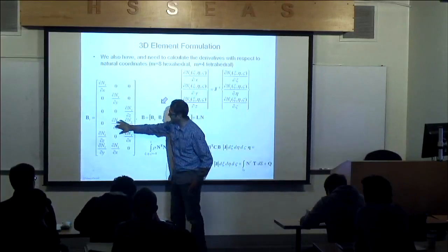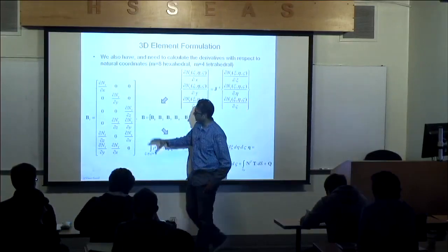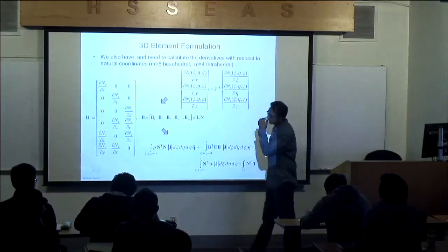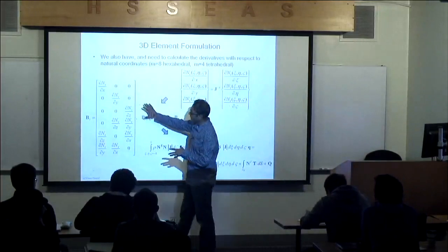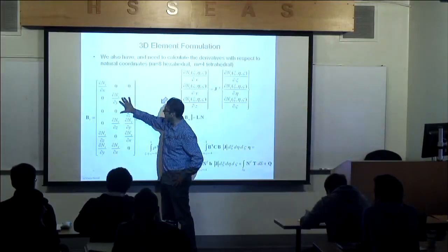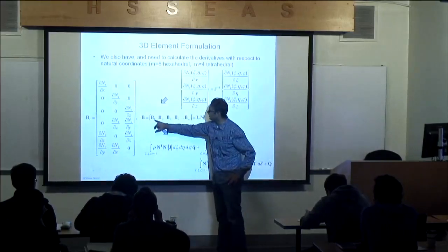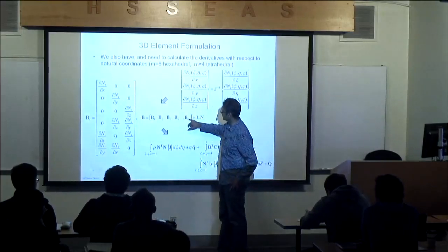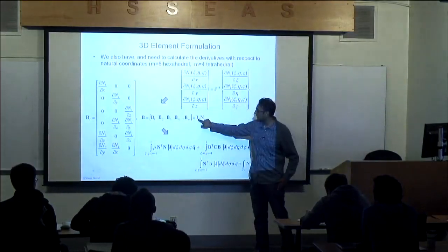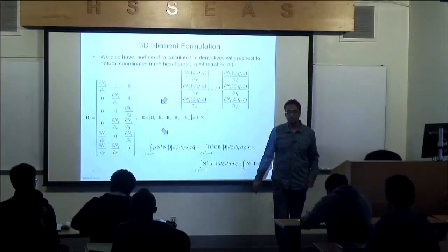And then same for the other ones, okay? You can calculate those very quickly. These are blocks. So this is for shape function 1. You have to repeat this for 2, 3, 4, 5, all these shape functions. So therefore, B bold becomes B1, B2, B3, up to Bm, depending on how many nodes you have. Okay? That is L bold N. That has not changed. Okay?